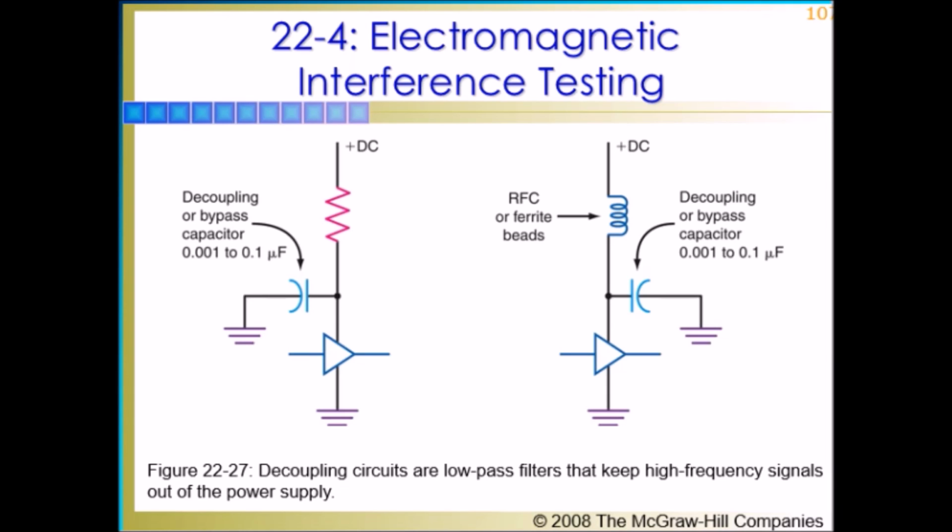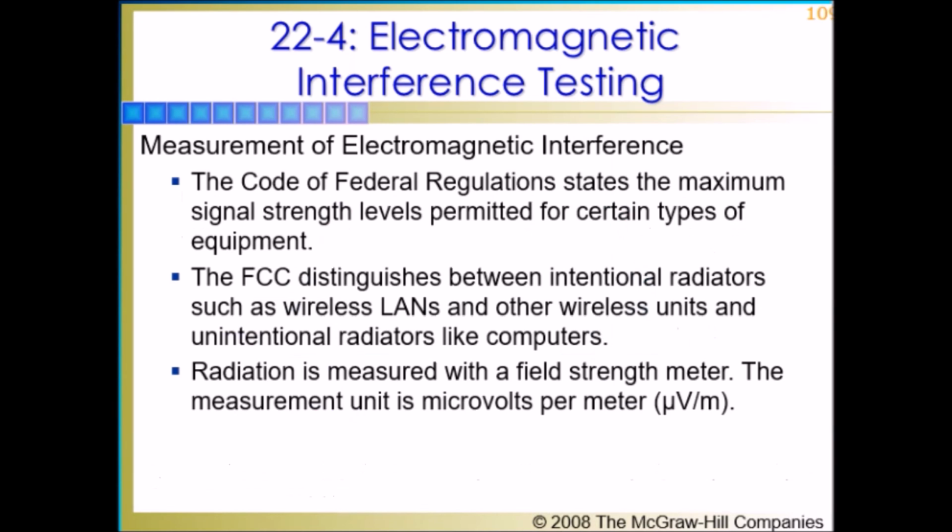The bypass capacitor must have very low impedance. For RF signals, ceramic or mica capacitors must be used. Any plastic dielectric or electrolytic capacitor used for decoupling must be accompanied by a parallel ceramic or mica capacitor to make filtering effective at the higher frequencies.